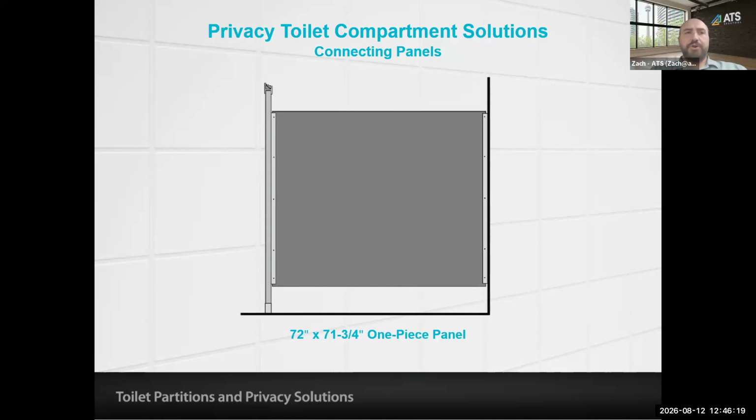And there are also a number of new clearance applications that come in, so consult the different diagrams that they have, because they have all sorts of different clearance applications now. So worth double checking there. I think it's like 62 inches with a wall mounted toilet and 64-inch depth with a floor mounted toilet. I think those are the two depths.